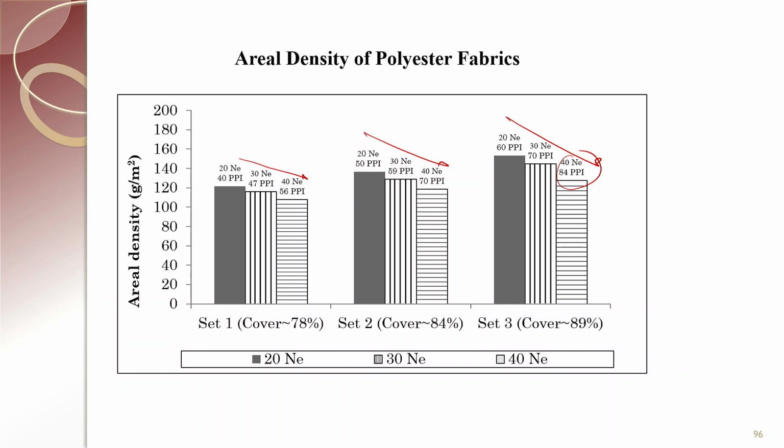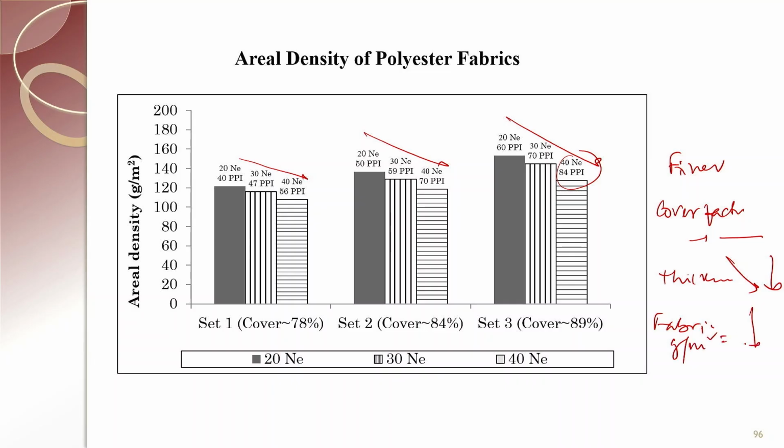Here, as yarn becomes finer, the cover factor, or percent cover, remains the same, yarn thickness reduces, and the fabric weight drops. So, that was our observation.